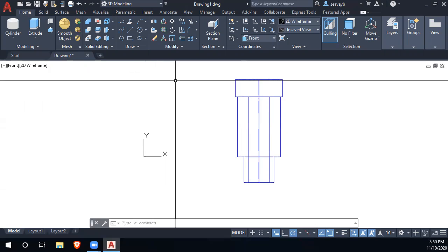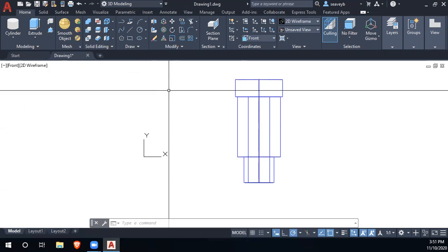So how about, look at how far it is. It looks like from the center of the cylinder to the center of the rounded end it's 1.875. So what if I start with a circle there, and then I could look at positioning it later. I'm just going to draw a circle here. So C, space.